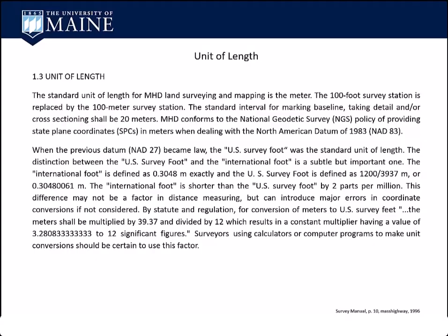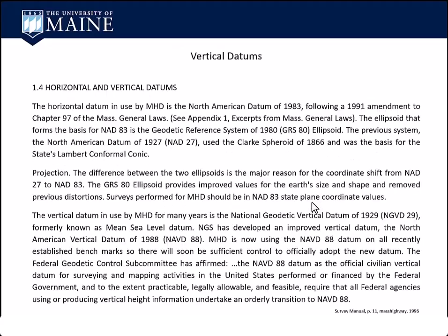It's not a big deal on a construction site perhaps, but if you were doing geodetic work, you start to introduce some real problems into the coordinates that you're working with. So just be aware that the conversions are different for U.S. foot, international foot, and all the NGS elevations were determined using the U.S. foot conversion factor.